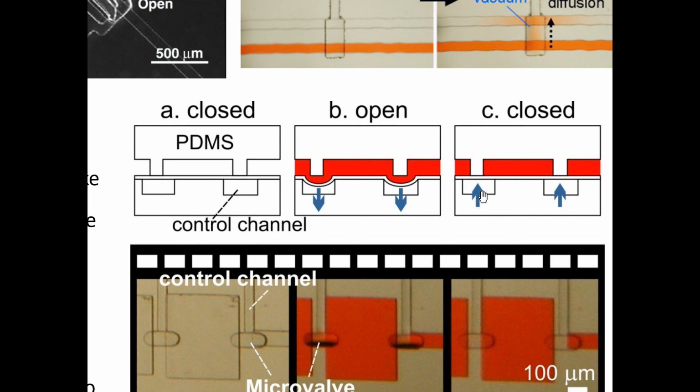If you apply positive pressure to it, then this membrane will be pushed towards a post, and this post is called the valve seat. The terminology is the valve seat, or the boss. Sometimes they call it a valve boss. That will obviously prevent the flow going through the channel. Now, this is a membrane that's being pushed down onto a post, so there's a very good contact that happens between here, so these valves form very good seals. That's one of the advantages of these doormat valves.